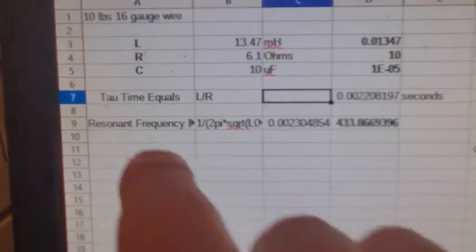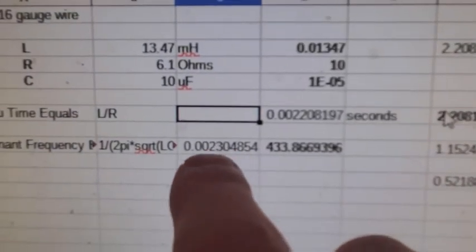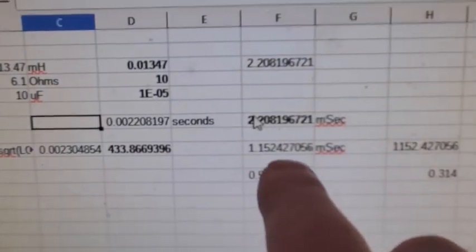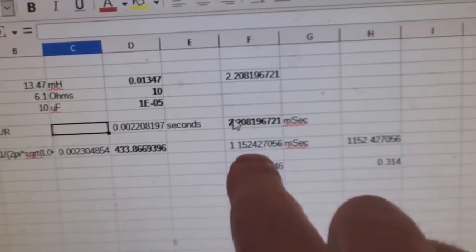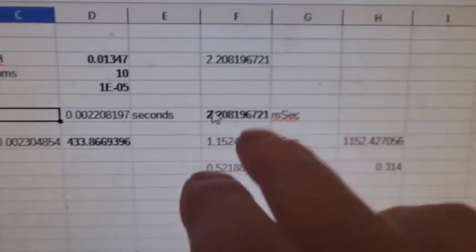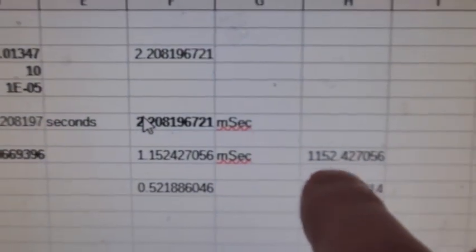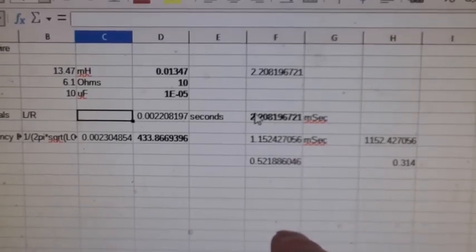And it also calculates for us the resonant frequency, and 1/2 pi. So here it's just giving you the time, and here it's giving you the hertz. And then here, this is actually the time that is 1/2 the resonant frequency. I just have it set up that way. So the reason I have it set up that way is that what this tells us is that if you connect the capacitor to here for 1,152 microseconds, then disconnect them, that's where the cap will be most negative.